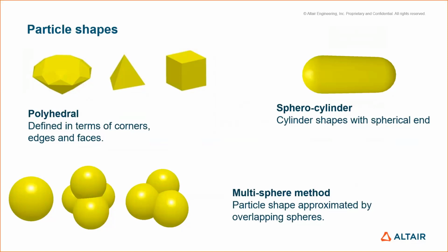There's different physics models suitable for this. So a simple computational element like a sphere is very well applicable. The multisphere shape is generally approximated by multiple overlapping or touching spheres whose centers are fixed relative to each other. The advantage of this method is that we get an approximation of an irregular shape while maintaining the computational efficiency and accuracy of the spheres.